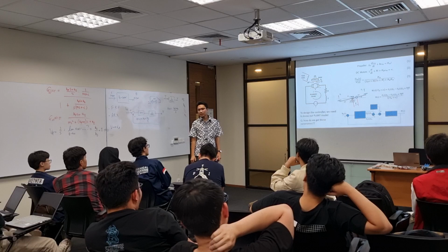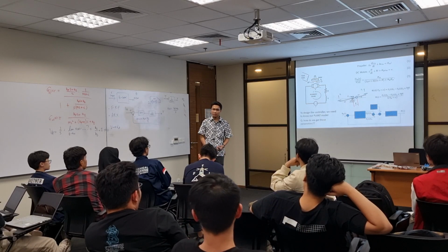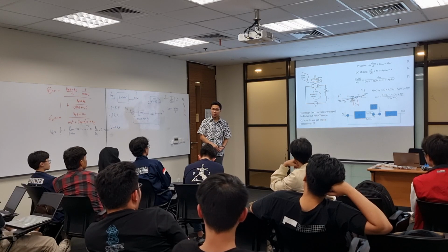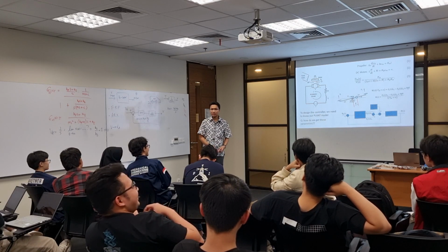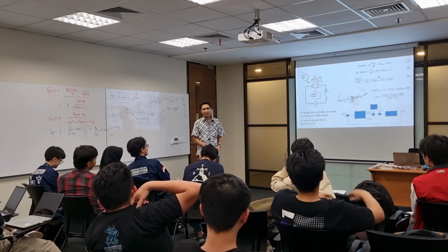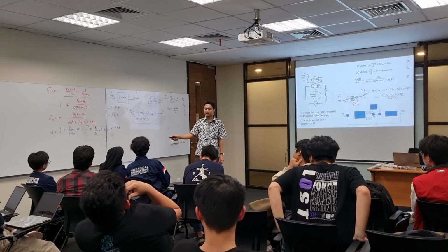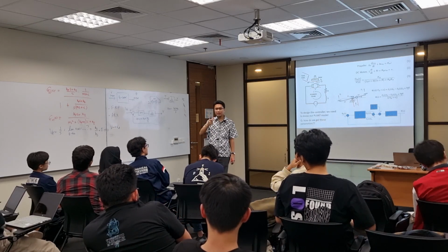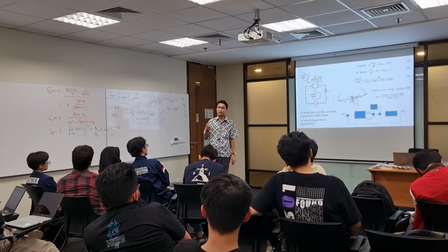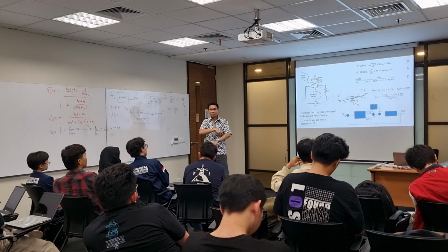If you use a certain controller like a PID controller, can you check the final value of theta? You can, right? It's just the skill of finding the closed loop transfer function. Once you obtain the closed loop transfer function, you can evaluate the final value theorem, to see whether the final value is affected by all of these parameters or not.